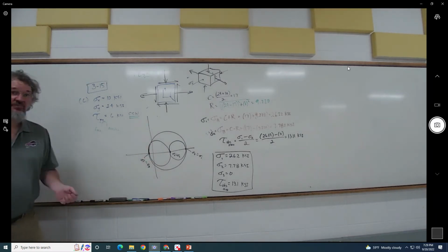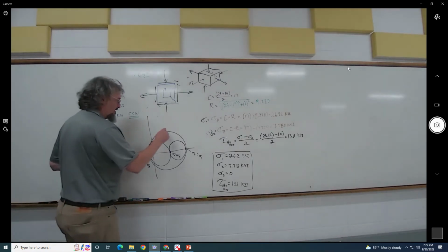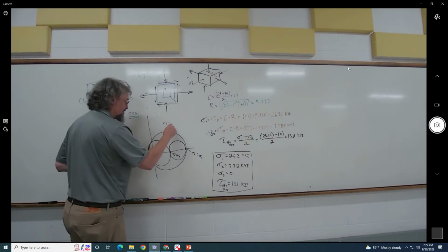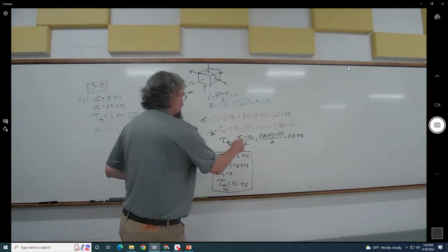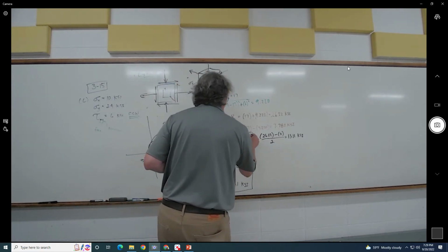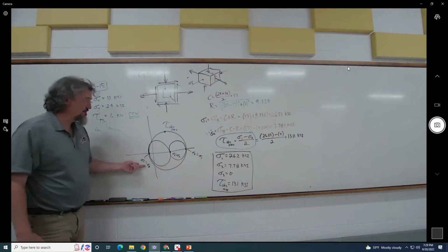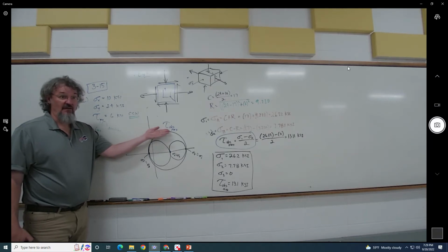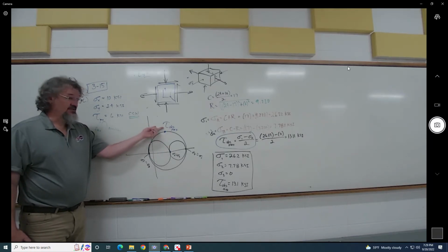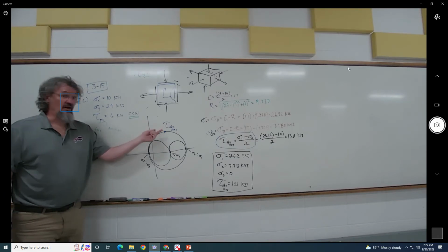That is possible and worth knowing about, because the most important aspect of this is this guy, because this is always true, right? The absolute maximum is always sigma 1 minus sigma 3, but sigma 3 might be negative, so that makes for a larger tau abs max. Because as we'll see in chapter 5, one of the failure theories is based on how large that number is.